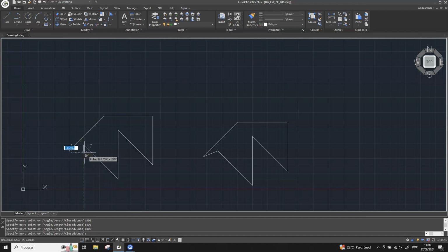However, we mentioned there was a line that had a unique angle, outside of our 45-degree guideline. We can see that the final line has an angle of 158 degrees. We could just select the endpoint and finish the drawing, but what if we need to use the 158-degree angle for another part of the project? It could be useful to have this angle appear as a guideline if it's going to be a consistent part of our drawing. So let's go back to the Polar Tracking settings